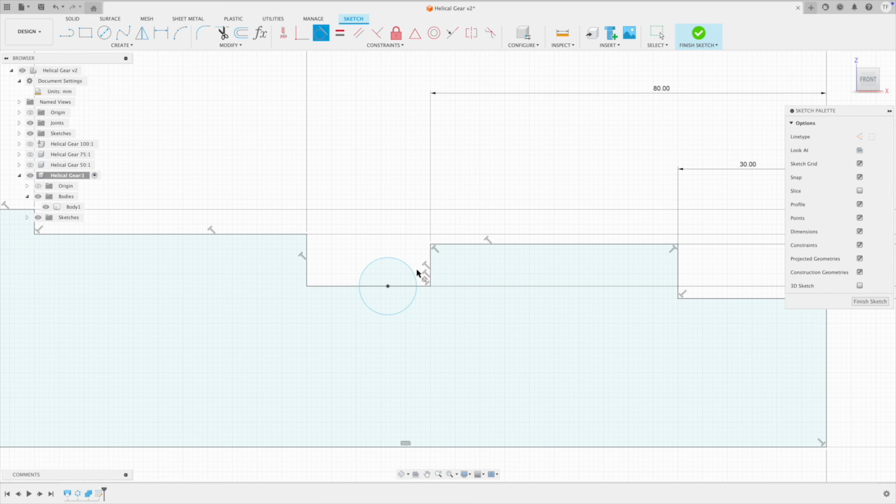Let's first of all make this circle tangent to this line. And you can see the center is constrained to this line right there. If it's not, you won't see this symbol if you click the center point. I'm just going to delete that symbol. And now you can see that the center point is movable, but the circle is still tangent to this line. So I want to constrain this point to that line. And all I'm going to do is go coincident. I'm going to pick that and that. You can see it constrains it together. Now let me show you one other thing. This frustrates people.